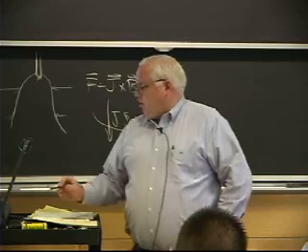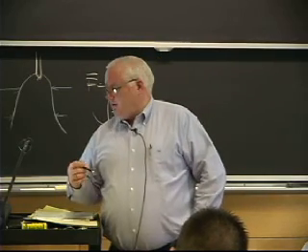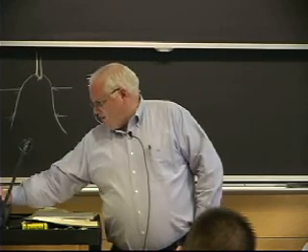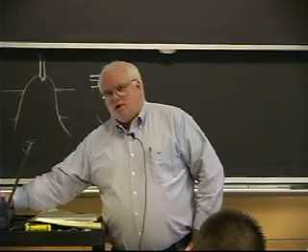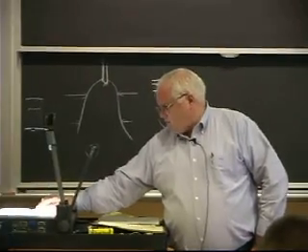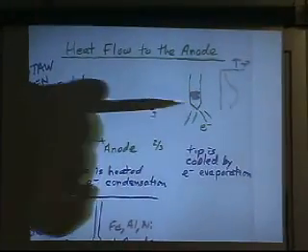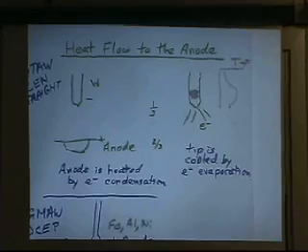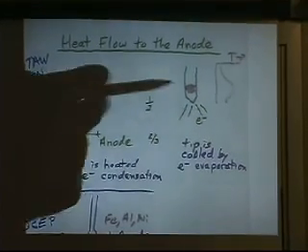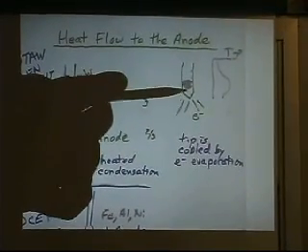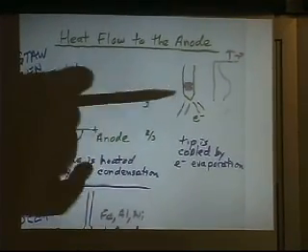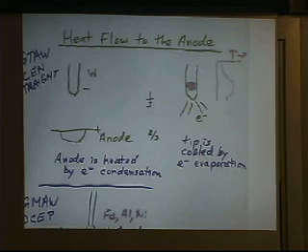And the reason, ordinarily, if you see a tungsten inclusion in steel or something on an X-ray, it'll show up as a little ball because you got too hot and you got a drop of tungsten in there. But the reason you get rectangular pieces of tungsten is because you actually melt off the whole tip. I mean, you melt it off back here, and you actually are getting a somewhat rectangular shape in your X-ray image. And he always explained it that way.